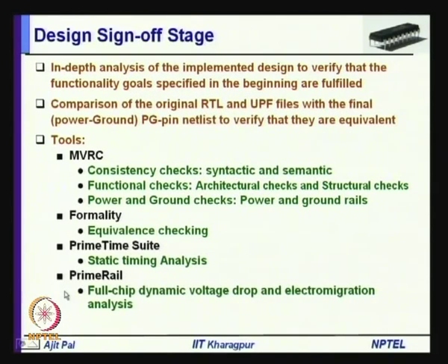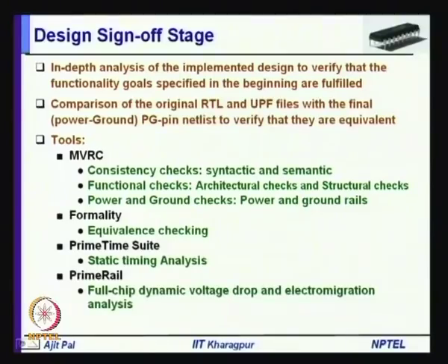Okay. Coming to the last stage, that is your design sign off stage. Whenever you are signing off, that means you are releasing the chip for commercial implementation. At this stage, you have to do certain things which are mentioned here. You have to perform in-depth analysis of the implemented design to verify that the functionality goals specified in the beginning with the help of UPF and VHDL or Verilog code are fulfilled or not.